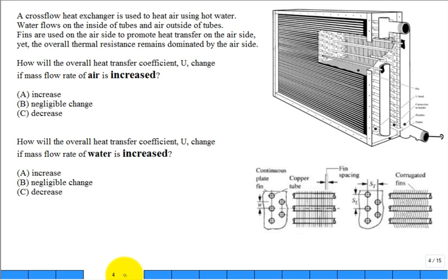Well, we have a lot of heat exchangers which are cross-flow. You've seen them. We talked about them before. Especially used to change the temperature of air. Air maybe that's supplied to a building, and maybe you use warm or hot water to heat it, or you could use cold water to cool the air in the winter or in the summer. So typically the water is supplied and returned, and then the air goes across. What do you do on the air side? You fin it. Why? The h on the air side is so low.